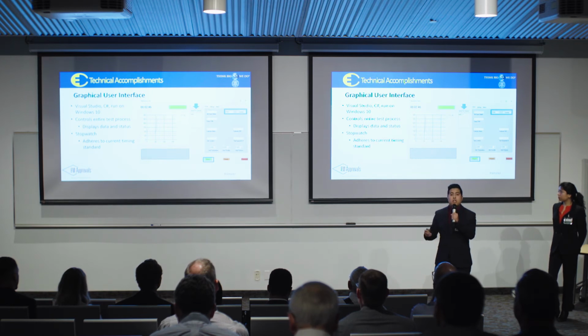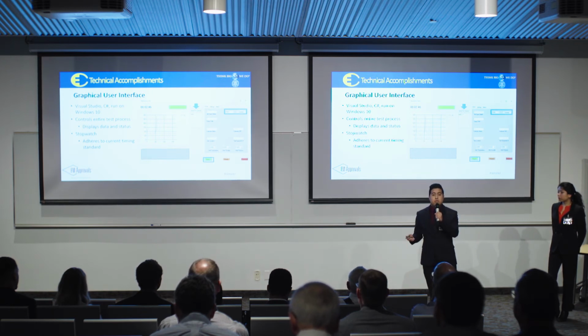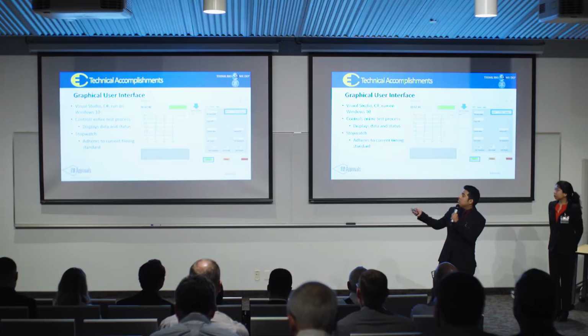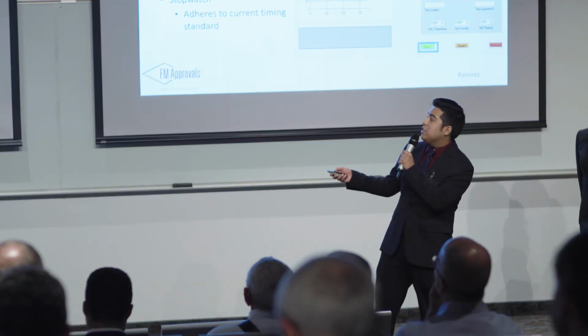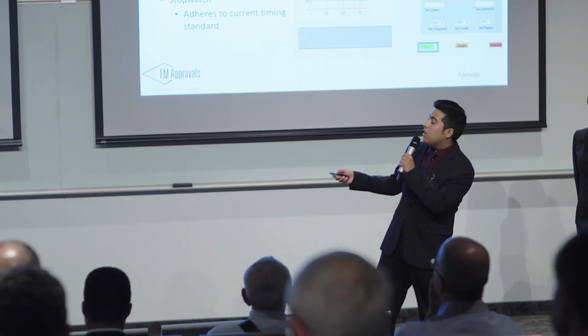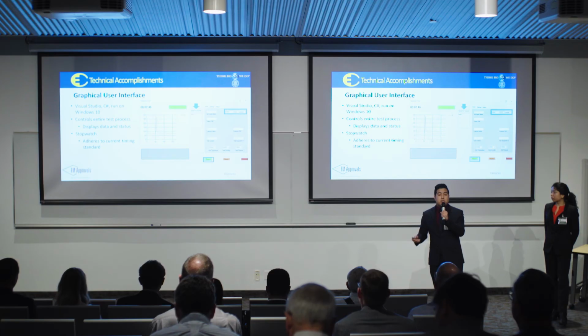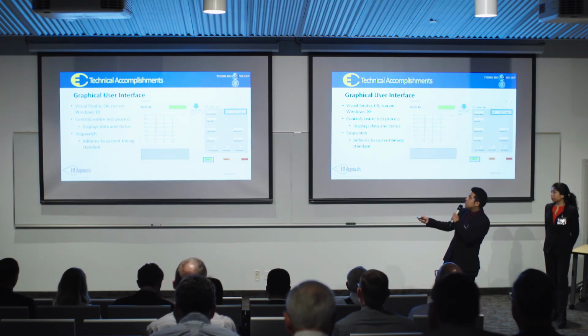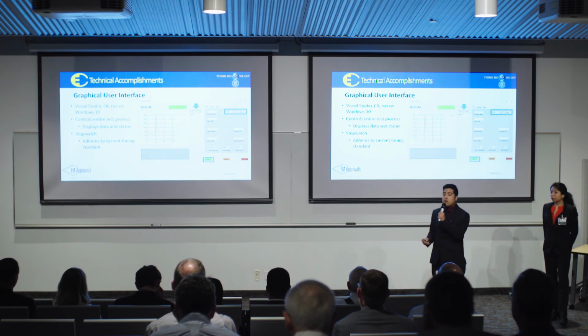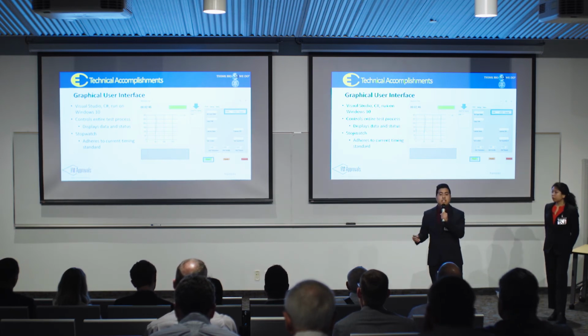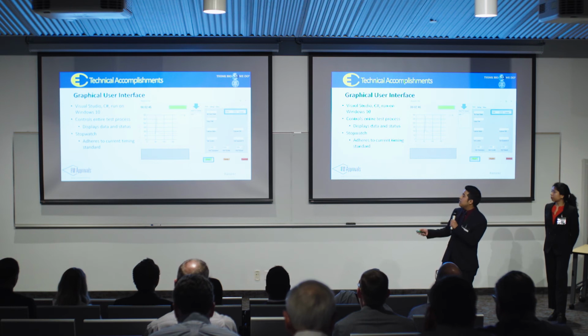Once we get to the portion of reading the lower explosive limit percentages, we implemented a feature that will graph each percentage every half second in real time until the 90 seconds is up. To eliminate the need of a physical stopwatch, we also implemented a stopwatch shown here in our GUI that currently adheres to the timing standards of 90 seconds for the LEL percentage readings.